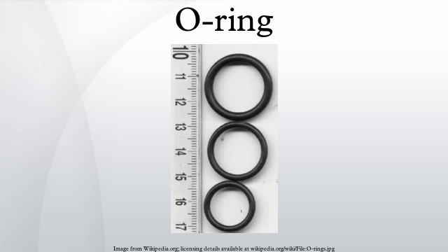Already, there are elastomers filled with nanocarbon and nano-PTFE and molded into O-rings used in high-performance applications. For example, carbon nanotubes are used in electrostatic dissipative applications and nano-PTFE is used in ultra-pure semiconductor applications. The use of nano-PTFE in fluoroelastomers and perfluoroelastomers improves abrasion resistance, lowers friction, lowers permeation, and can act as clean filler.